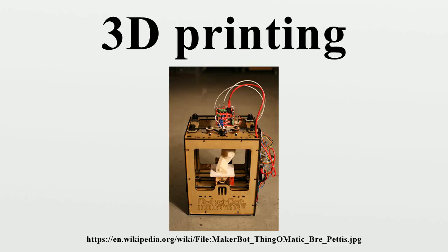Lamination. In some printers, paper can be used as the build material, resulting in a lower cost to print. During the 1990s, some companies marketed printers that cut cross-sections out of special adhesive-coated paper using a carbon dioxide laser and then laminated them together. In 2005, MCOR Technologies Limited developed a different process using ordinary sheets of office paper, a tungsten carbide blade to cut the shape, and selective deposition of adhesive and pressure to bond the prototype. There are also a number of companies selling printers that print laminated objects using thin plastic and metal sheets.